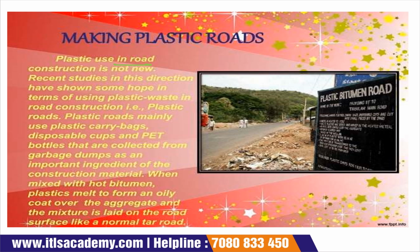Using plastic in road construction is not a new concept, but recent studies in this direction have shown some hope in the form of using plastic waste in road construction, that is, plastic roads. Plastic carry bags, disposable cups and PET collected from the garbage dump are important ingredients of the construction material. When mixed with hot bitumen, plastic melts to form an oily coat over the aggregate, and the mixture is laid on the road surface like a normal tar road.